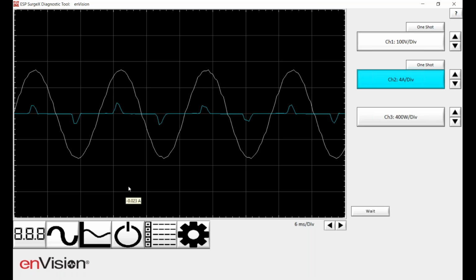What are some of the remedies that they can do? Well, the first thing I would do would be to split the load, balance the load. If you have another circuit available, move things to the other circuit. You could install a new circuit.